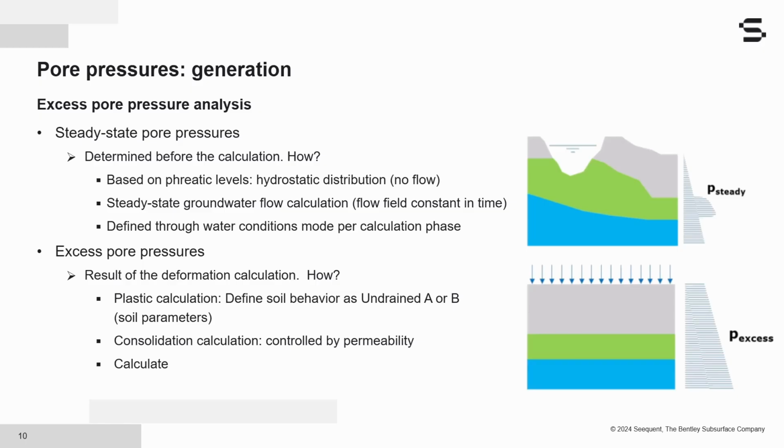Now, as we have mentioned in the previous slide, it is important to note that the pore water pressures do not change with time during a displacement or consolidation analysis. However, it is possible to define or redefine the hydraulic boundary conditions in an analysis stage in order to establish a new steady state pore pressure distribution at different phases.